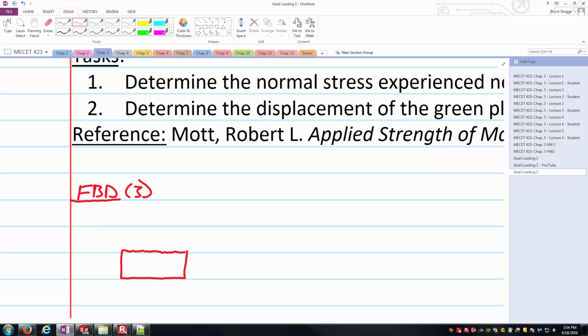I'm going to make an assumption that it's in tension. And so the way I'm going to do that is I'm going to draw this force right here. Notice it is perpendicular to the exposed surface of the material that I made with my free body diagram cut, and I'm going to call that F3. And so this is the internal force carried by section 3.